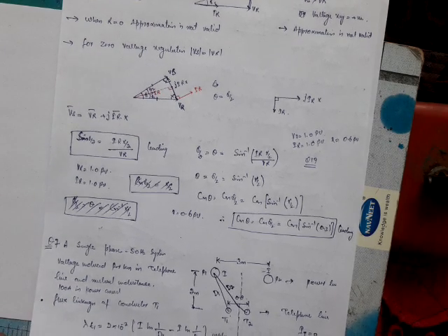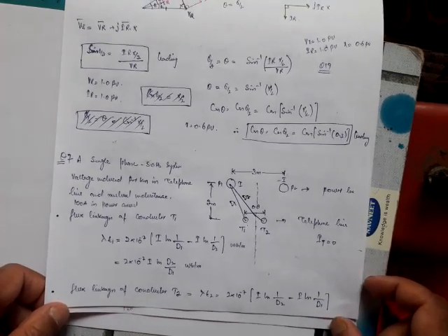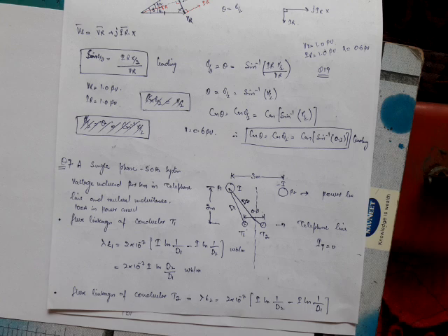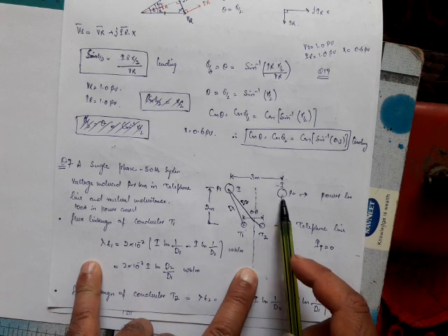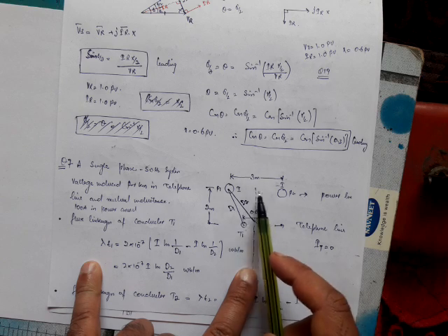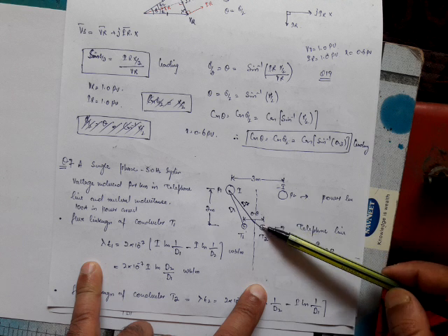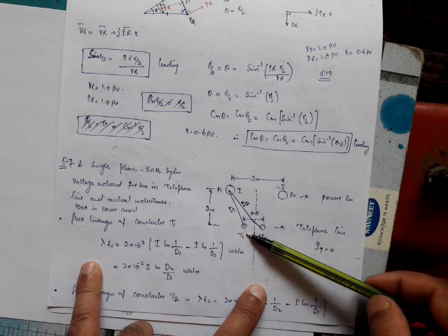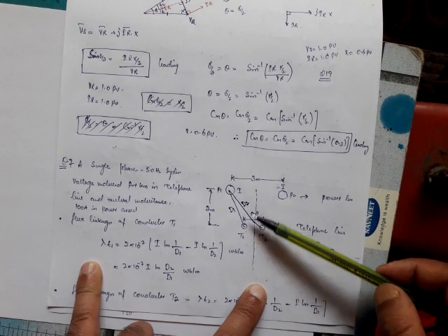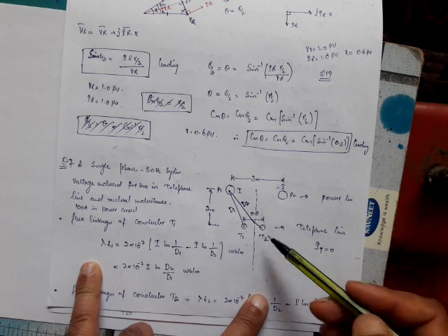This was simple. Now coming back to the other question, which is actually from the parameters of the transmission line. In this case we have a simple single phase transmission line whose power conductors are P1 and P2, which are 3 meters apart from each other, and placed below them is a telephone line of two conductors T1 and T2. They are placed 2 meters below, as shown here, and they are 0.8 meter apart from each other. They are symmetrically placed below.